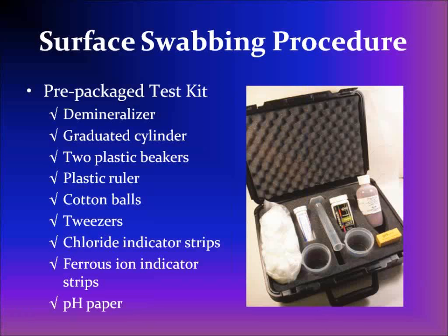The first extraction procedure that I'm going to be describing is the swabbing method. It's not the best, but it was probably the first method ever marketed for the extraction of soluble salt contamination on surfaces. Some work done by SSPC indicated that it actually produces a very low extraction efficiency, arguably the worst of all the methods described today. However, it was the first, it was the easiest to improve upon, and certainly industry has done that.